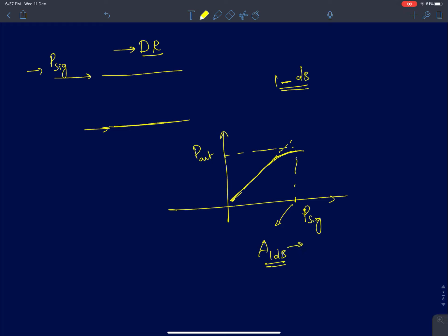The units were volts. We expressed it as a peak value in volts. I told you we can also express it in dBm, provided you mention the ohm system that was used to represent it. But if a question says express it in volts, express it in volts, or in dBm, express it only in dBm. Look at the question paper: what am I asking specifically? Just express it accordingly.